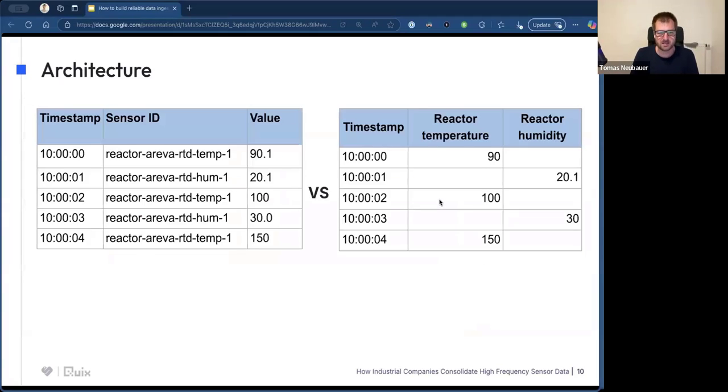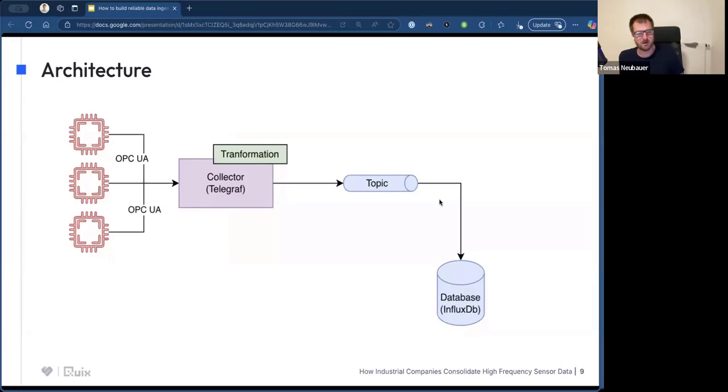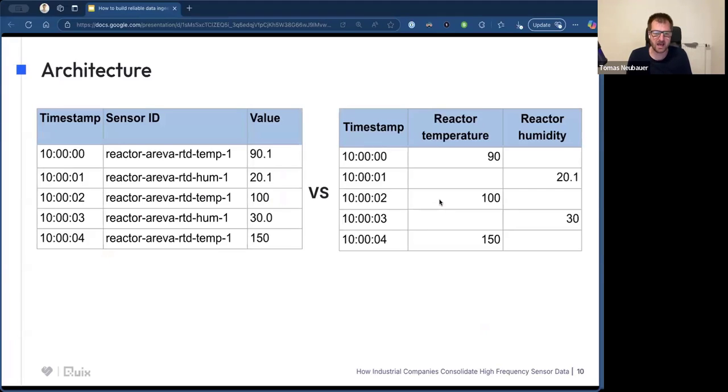So moving back to transformations, let's talk about these transformations because there's lots of stuff that makes sense in an industrial monitoring like this. So first thing is how the data is coming in. What you see on the left is a very typical MQTT style structure, where the topic topology represents a sensor topology in the machine.